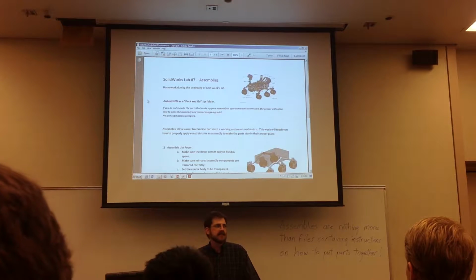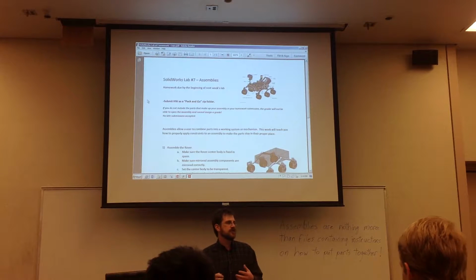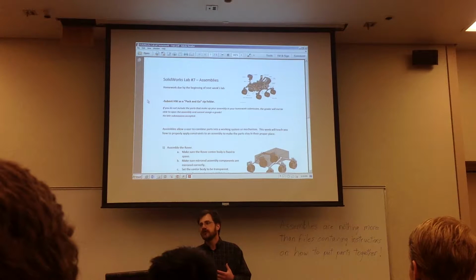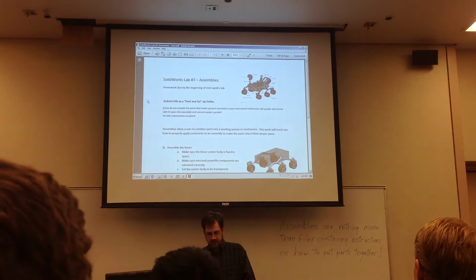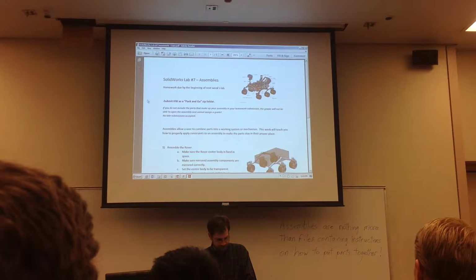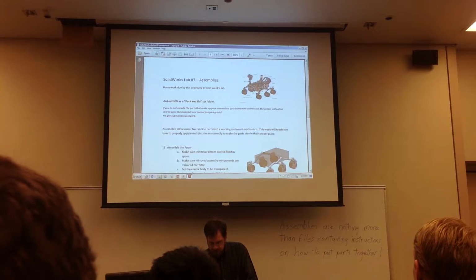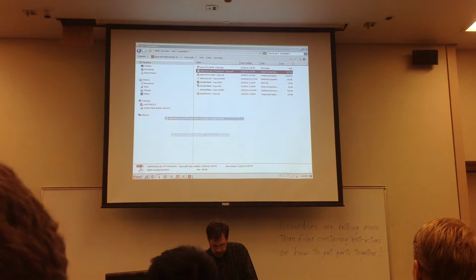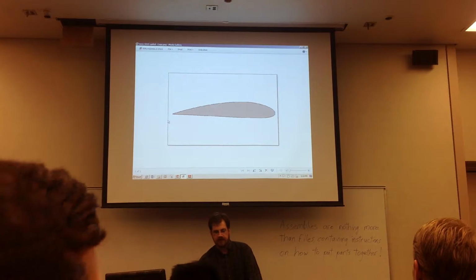And what's nice about sketch blocks is each time you insert a sketch block, SolidWorks lets you scale the sketch block, make it larger or smaller, and you can also specify an angle of rotation for that sketch block if you need to change its orientation. So to demonstrate those two tools, I'm going to use this airfoil as an example.